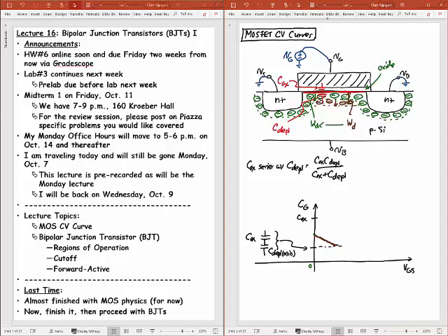And so if I form that inversion layer, what's going to happen immediately is that all of this is going to rise to the capacitance just being Cox, because now that inversion layer is right there, and my capacitance is really between the conductor of the gate and that inversion layer. So that means if I project out Cox here, this curve will basically just come right back up.